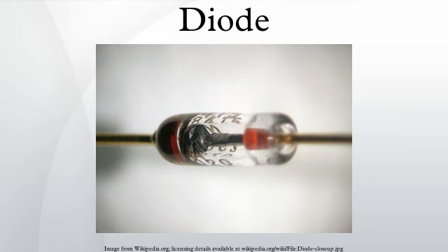However, the width of the depletion region cannot grow without limit. For each electron-hole pair that recombines, a positively charged dopant ion is left behind in the N-doped region, and a negatively charged dopant ion is left behind in the P-doped region. As recombination proceeds, more ions are created, and an increasing electric field develops through the depletion zone that acts to slow and then finally stop recombination. At this point, there is a built-in potential across the depletion zone.